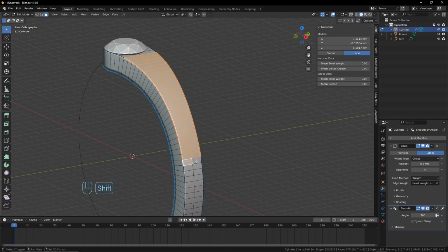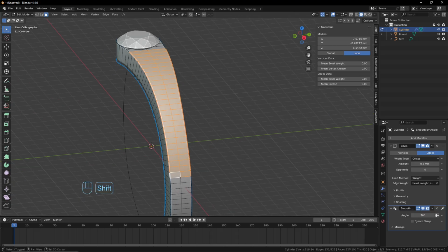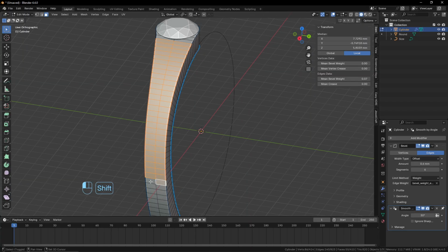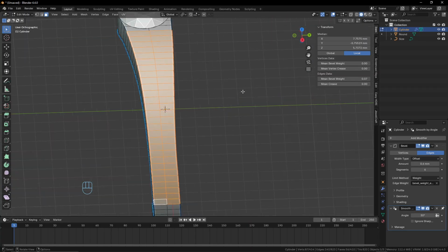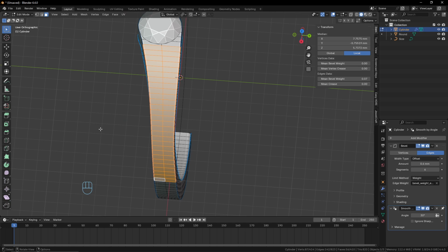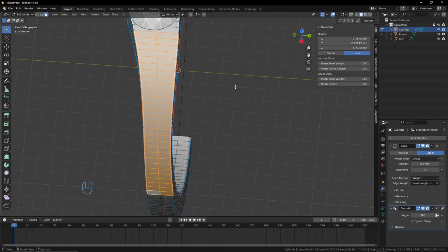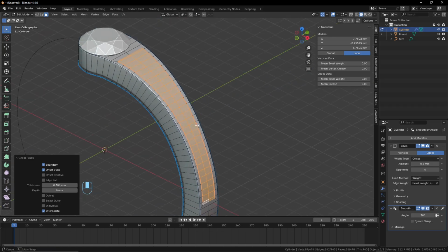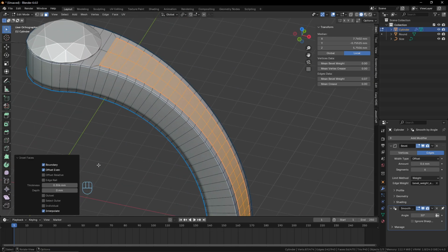It depends on the number of gems that you want to add and everything. But let's say we would like to have this rail until half of it there. So now I will use the Y here. The Y is the inset, not the bevel here, the inset face. So yeah, I will add an inset into that area. Okay. And this inset, I will extrude it. So now that I have this inset like this, I can extrude this inside.